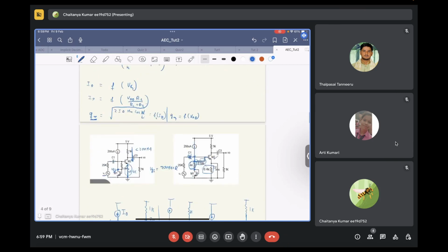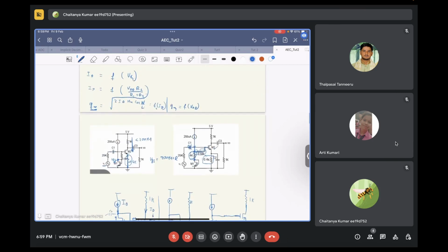And the third circuit became susceptible to VDD variation and systematic variation in VT of transistors M1 and M2, and became immune to some degree to mismatch in VT of transistors M1 and M2. So this is the benefit of going from the first circuit to the second to the third. Is this clear? Yes, perfect, sir.